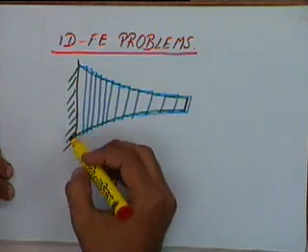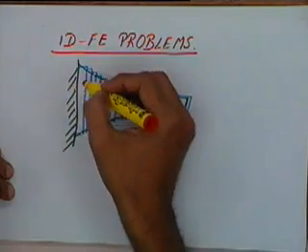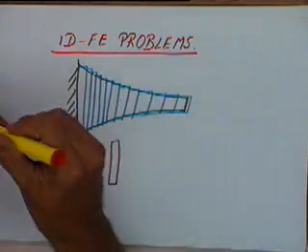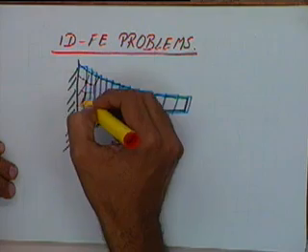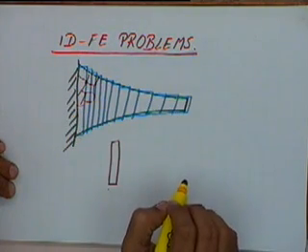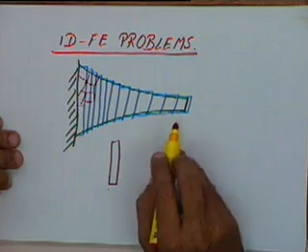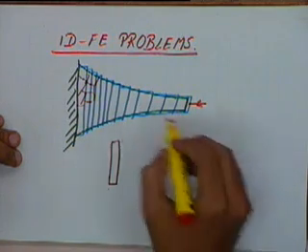If you want to formulate the same thing as a two dimensional problem, then we can approximate it by triangles or quadrilaterals or something like that. Those could look maybe something like this. But right now we are just talking about a simple one dimensional formulation of this problem. So we will assume that there is no variation in the other two dimensions and all loads are also only acting in one direction. All the loads will also be acting in the x direction only.